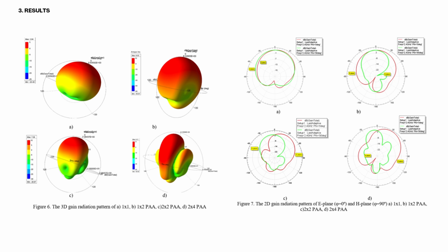In the two-element patch antenna array scenario, the 2D plot demonstrates an even gain distribution and wide radiation angle, similar to SPA, with an HPBW value spanning 88 degrees from minus 40 to 49 degrees. Additionally, a more pronounced side lobe and back lobe was observed from the H-plane in the two-element PAA.